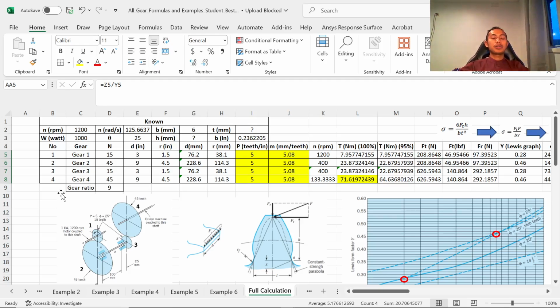For an increaser, we want more velocity at the output and low torque, just the opposite. We can actually reverse some gearbox configurations, such as planetary or multi-stage spur gear gearboxes. But for rack and pinion, it's very difficult to reverse.